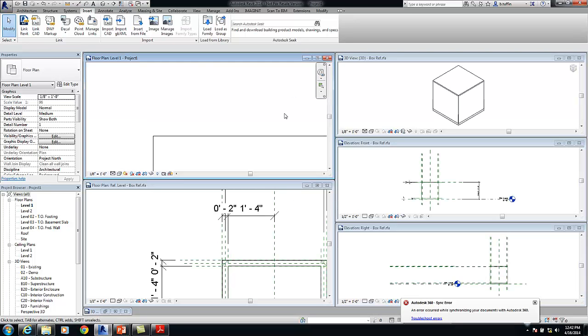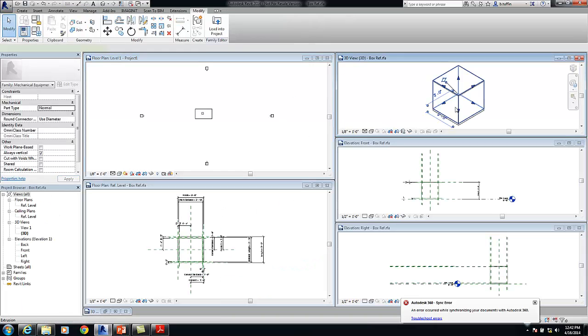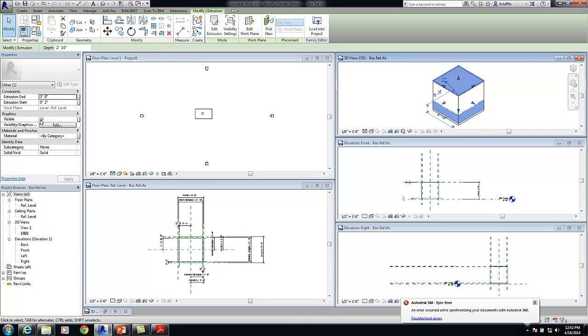As I'm working inside of here, every single object, everything we create, has a visibility associated with it. So, let's get back there. A visibility. And with that visibility, I can tie it to a parameter. So what I can do is create an on-off parameter. Show clear zone requirements, or don't show them. Check it on or off. That's a great way to turn things on and off, just linking them.